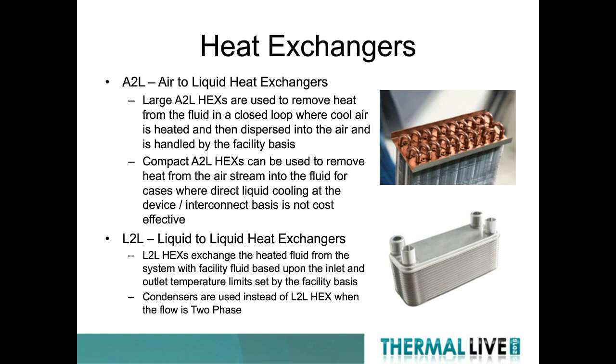For the liquid-to-liquid heat exchangers, we typically use a plate fin approach where it's stainless steel plates, they're brazed together. This is used in the radiative floor heating industry, so it's fairly common. And so this, we use to exchange the heated fluid in our loop with the system using facility fluid based on the inlet and outlet temperature limits set by that facility. And as I mentioned, condensers could be used instead of the liquid-to-liquid heat exchanger when the flow is two-phase.